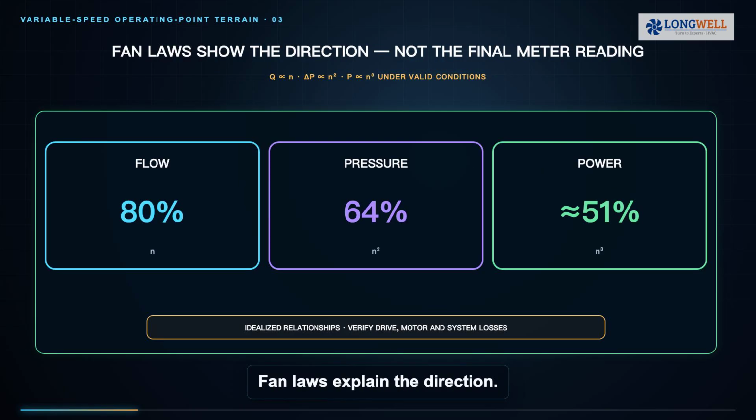Fan laws explain the direction. Under valid similarity conditions, airflow follows speed, pressure follows speed squared, and fan power approximately follows speed cubed. At 80% speed, that suggests 80% flow, 64% pressure, and about 51% idealized fan power, not necessarily electrical input at the meter.